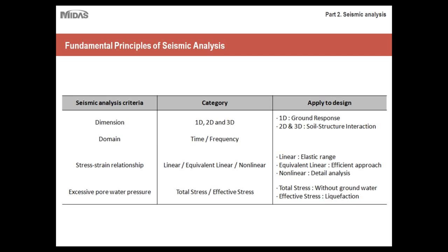We won't be going into detail about liquefaction, because that's a deeper concept that would require its own presentation. But keep in mind that undrained soil conditions with seismic loading create a very dangerous and unpredictable environment for your structure. For now, we'll keep it simple and focus mainly on drained analysis. The analysis procedures that we'll discuss assume that the soil is drained, so without groundwater.